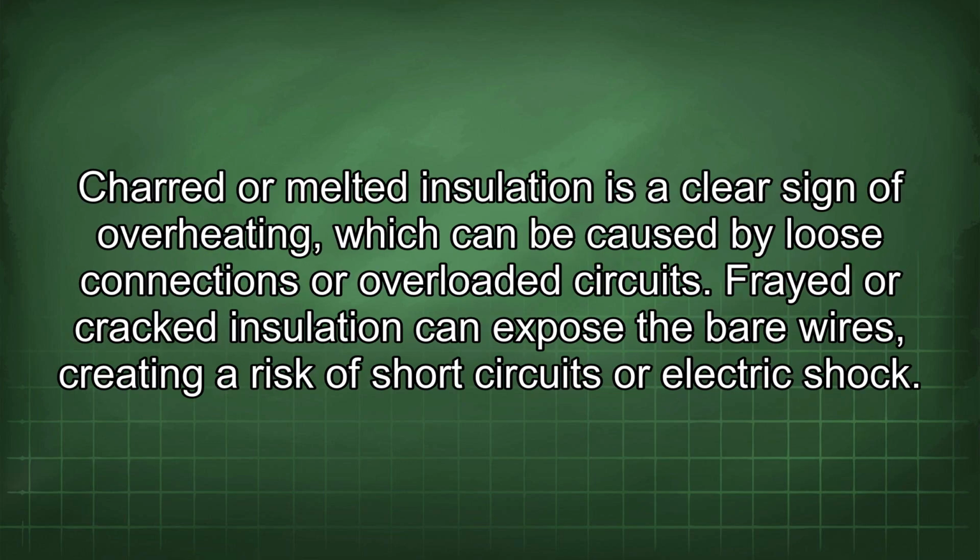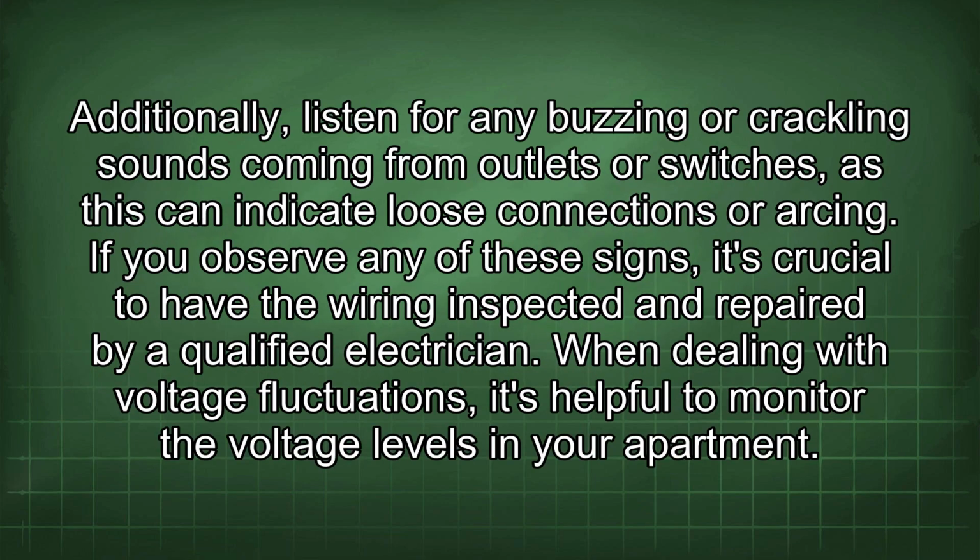Charred or melted insulation is a clear sign of overheating, which can be caused by loose connections or overloaded circuits. Frayed or cracked insulation can expose the bare wires, creating a risk of short circuits or electric shock. Additionally, listen for any buzzing or crackling sounds coming from outlets or switches, as this can indicate loose connections or arcing. If you observe any of these signs, it's crucial to have the wiring inspected and repaired by a qualified electrician.